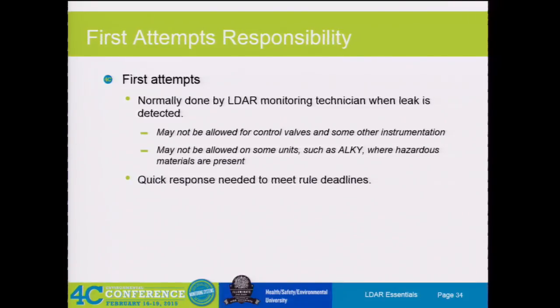Yeah. A lot of sites I've been to recently have moved to that because they had LDAR technicians who didn't know what they were doing. I found a leak, I fixed the leak. Well, they over-tighten so badly that when that valve is in play or there's an operational issue going on, now your operations and maintenance guys can't even function the valve because it is so over-tightened.